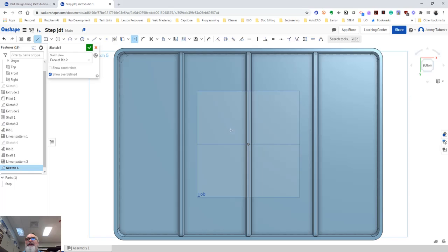Now to me, this is the easiest way to do this. If I move my mouse on top of the origin, now don't click it yet. If I just move that to the side, notice the little yellow dotted line that follows it, and the constraint is telling me that it is horizontal. So I'm going to come outside of here, click, and drag that back across there, and that way I know that it is a horizontal line through the center. Now I'm going to uncheck my construction line and just check my line tool.